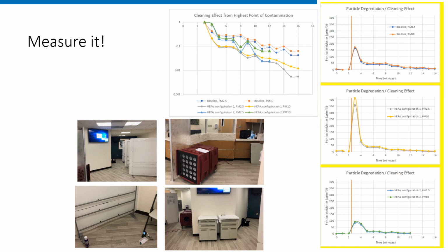This is only a 300 square foot space, so 1,000 CFM is more like 15 air changes. And the orientation of this HEPA unit in the space, i.e. the direction we pointed it, made a big difference, particularly in the immediate reaction to the fouling. You can see scenario 2 has a big spike, which is caused by the air path.